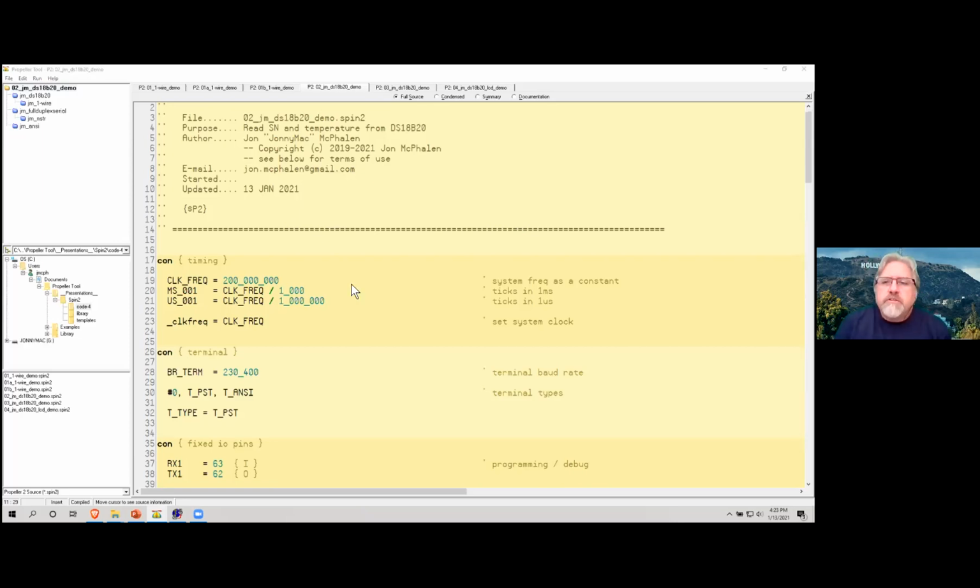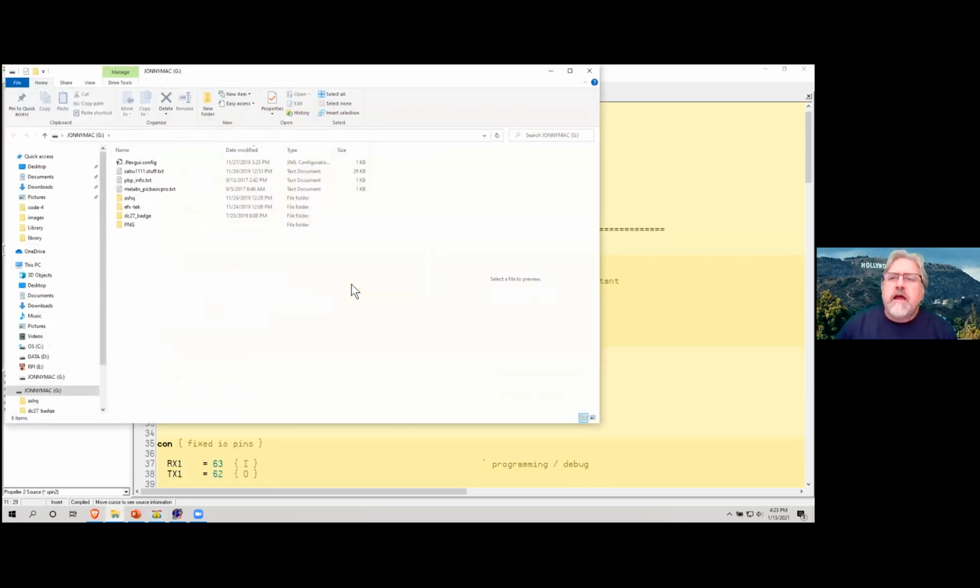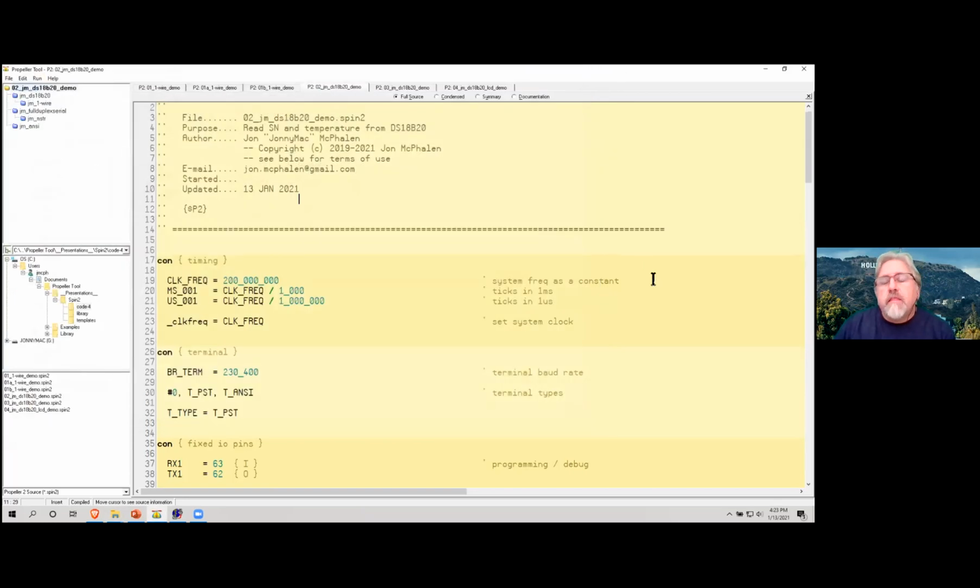Now, the one-wire search is really hairy, and I haven't got it sorted out for the Propeller yet. The funny thing is I found a BASIC Stamp file that does it. So I did figure this out once, but it's a little on the gnarly side. So maybe I was a little too specific. Reset will not tell you how many devices there are, but there is an algorithm that lets you do a one-wire search that will identify all of the unique devices on the bus. So I am working on that. When I get it done, I'll put it in the forums.